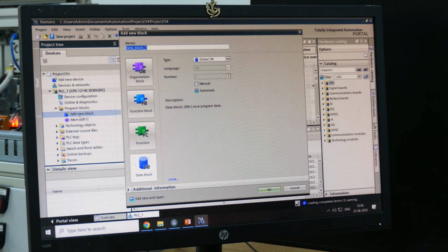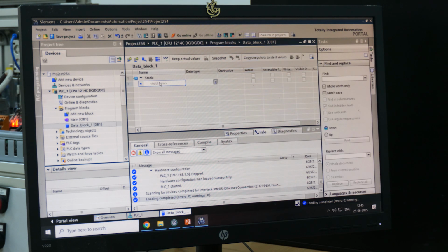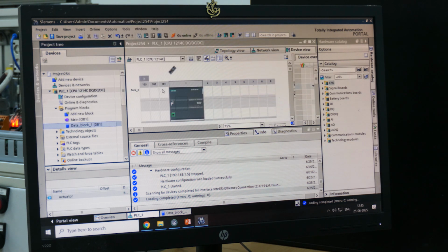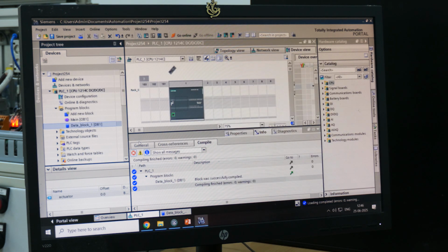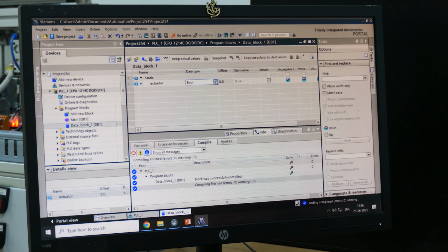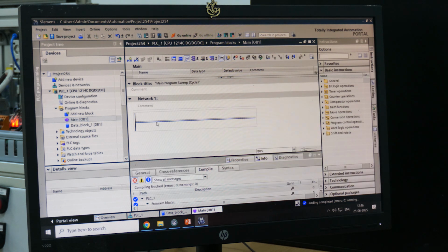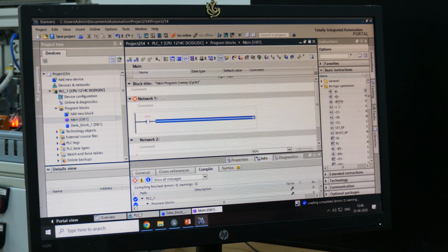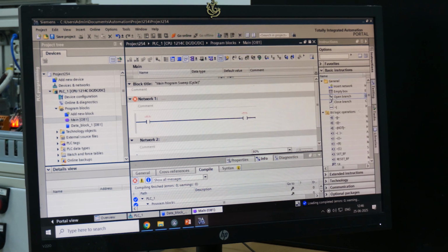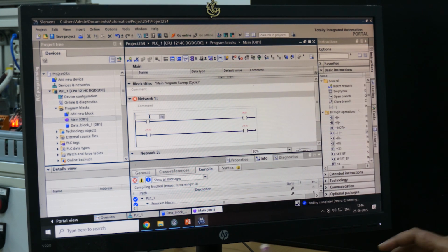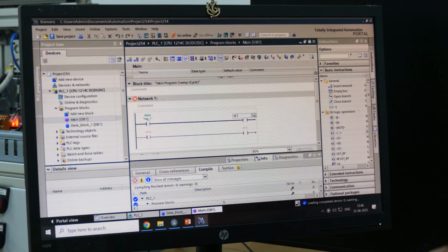What we do first is select the PLC, configure the PLC and connect our software to the hardware configuration. The next thing is to create a program block. We require a data block to analyze whatever data is happening in the hardware to reach the cloud. Whichever data type it is, a boolean or an integer or otherwise, give the data type and then save it. Okay, and minimize. Once it is there, we need to give access to this so that it reaches the cloud.